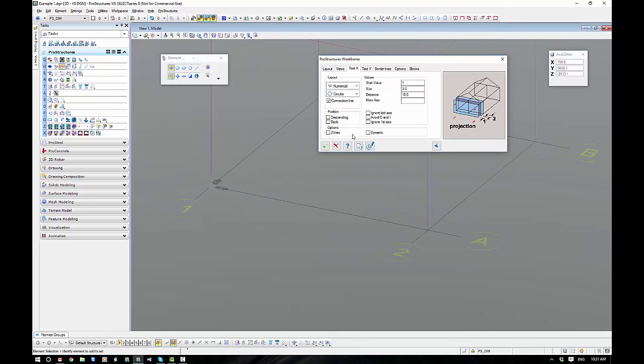Okay. We have our descending, which will flip the 1 and 2 over there. So it goes 2, 1. I can ignore the first axis, ignore the last axis. You would use this in an instance where maybe one axis is a long, long way away and you just want to shrink everything down, or alternatively you could turn it off for an existing building.